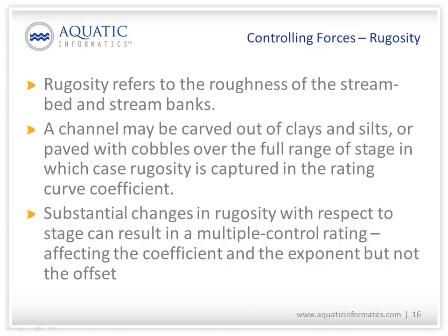As the stage rises, your composite roughness changes. If the transition from one composite roughness value to another is fairly abrupt, you may need to have a break point in your rating curve. If your stream bed is particularly rough, you might need the curve to plot a little bit further to the left at one stage, and then above some threshold a little bit further to the right if your stream banks are less rough than your stream bed, for example.